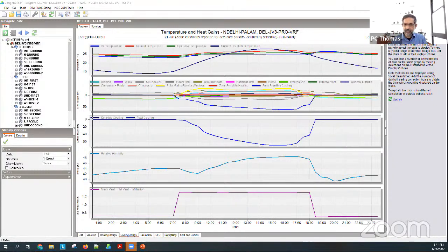Underfloor systems, you can't have a very cold supply air temperature. If you do, you'll freeze the ankles of people. So you have to supply at a much higher temperature, maybe 18 degrees, 19 degrees. When you supply air at that high temperature, you have very little capability of dehumidifying the air. So you can get moist air coming into the space, which is again not very good.